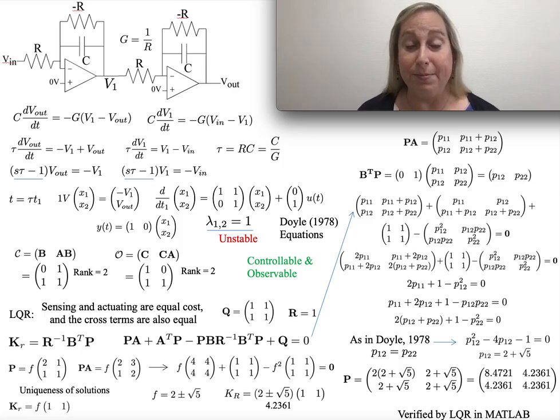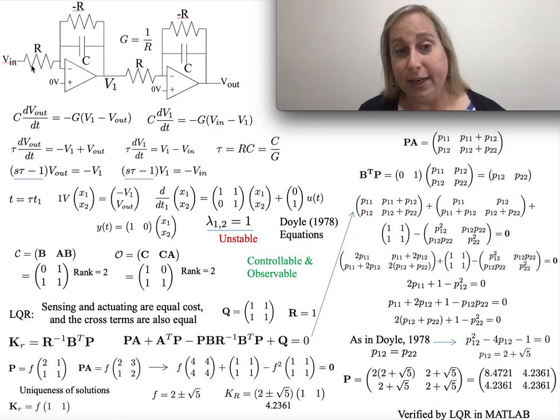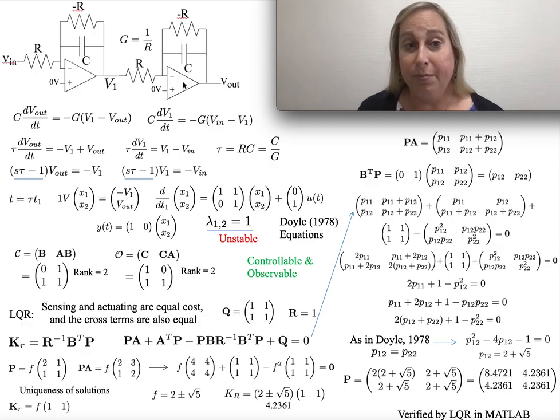Going to be one with op amps that's going to be a focus towards looking at a control problem. And what's kind of nice with circuits and control is that they can go one to each other and they interrelate to each other. One of the interesting ones is thinking about the circuit up here, where I have cascaded two sections, both of which have an R, a C, and a minus R. The minus R is going to give us the instability, and typically if you're saying I've got an unstable pole, this is probably where I'm representing it.